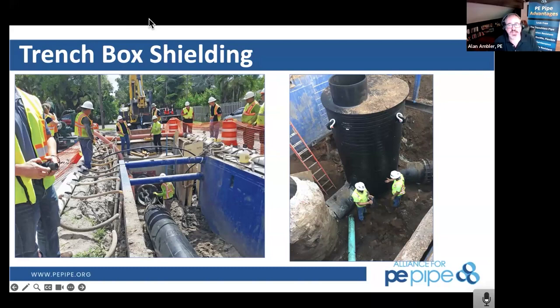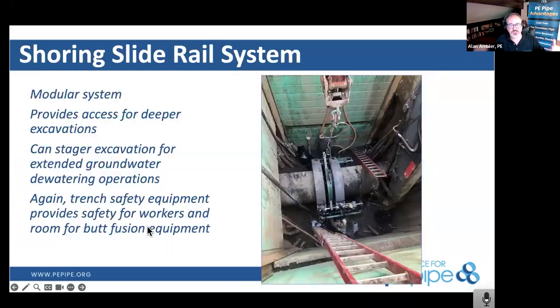So just like your precast concrete manholes, you need to know what angle and what invert elevation that pipe is coming in at through a gravity sewer. So we're going to measure all of that in advance. Then it would be fabricated off site and brought to your project site. They're going to do the same thing with an HDPE manhole.